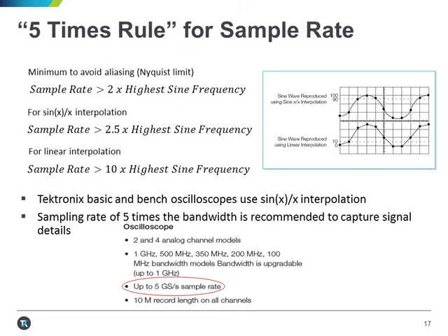Tektronix recommends another rule of 5 here. We suggest your sample rate should be 5 times faster than the highest frequency component of interest. This will give good detail and is more than enough to avoid aliasing. Most of the scopes maintain this relationship, and as an example, I've clipped the datasheet for a 500 megahertz oscilloscope. The fastest sampling rate of 2.5 gigasamples per second allows you to capture 5 samples of each cycle of a 500 megahertz sine wave.